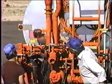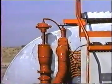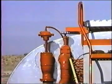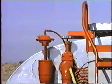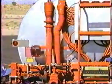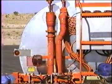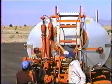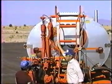Finally, where we want it to go is up that line. I'll point that out with my pointer here. We're going up this line to the gate valve on the top left of the tank, and that is the tank circulate valve, and it's labeled that if you got up and looked at the label. Okay, that line goes to the very front bottom of the tank, and it's there just to circulate material throughout the tank. That is, we're pulling out of the back, in the bottom, out the top, up that line, and that line returns it to the front of the tank. Okay, that's the only thing that we're going to use that valve for.